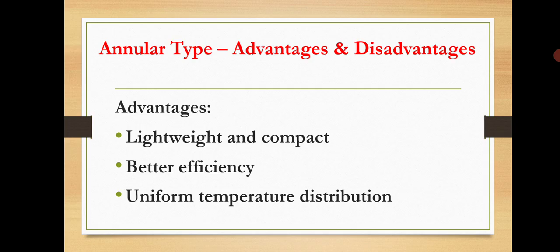Second point, better efficiency. Air flows smoothly without interruption. Less pressure loss compared to can type chamber. It improves fuel burning and overall engine performance. It leads to more efficient combustion.